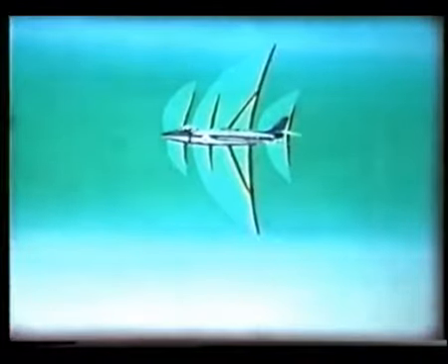In the second film of this series, the transonic range was described, in which the airflow round the aircraft is mixed, part subsonic, part supersonic. The dark green represents regions of subsonic flow, the light green supersonic. Shock waves are shown in red. This film is about the much more straightforward supersonic range, where the main flow everywhere is supersonic, shown, as before, in light green.